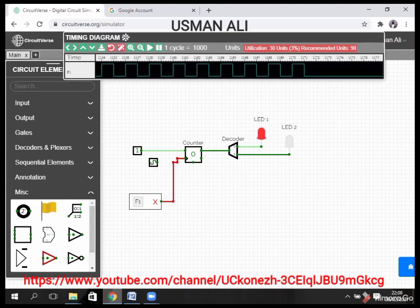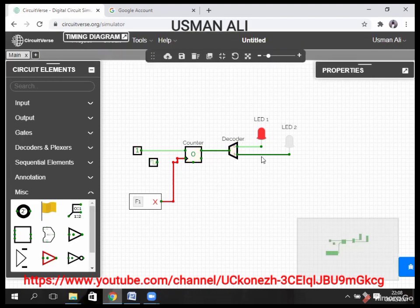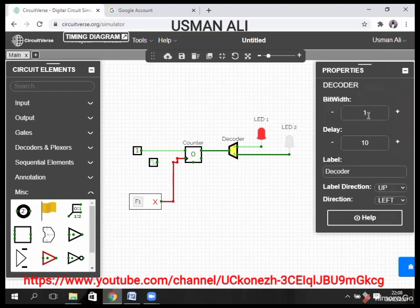In our next task, we have to increase the LED lights. We click on the decoder. Here is the bandwidth of the decoder, which is equal to 1. It means 0 and 1, and now you have to change it to 2. Now you see our signal outputs increase because of our bandwidth 2. We decode 2 with the formula 2 multiplied by 2, which is 4. Here you see 1, 2, 3, 4.